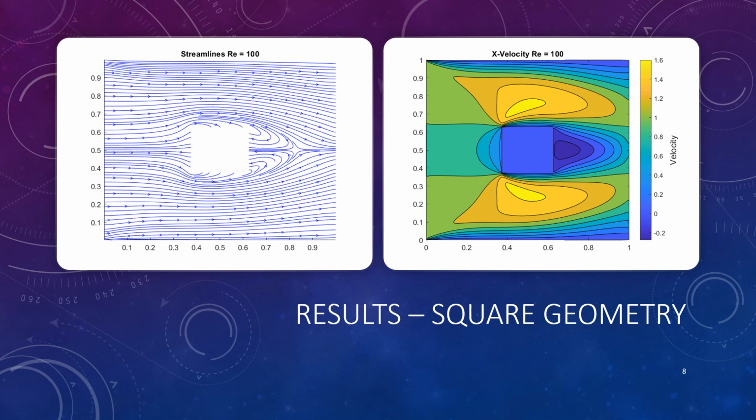Spatial convergence was tested using multiple grid sizes from 26 by 26 to 201 by 201. Generally, 101 nodes was acceptable for these studies, and spatial convergence rate was around 1.3.